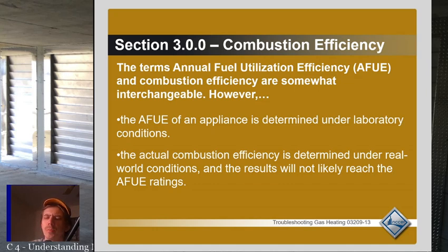Or if you need to know your BTU output in general, you need to know the AFUE of the furnace so that you can calculate what your actual output is. So if it's an 80,000 BTU furnace and your AFUE is 80%, then that 80,000 BTU furnace will actually put out 64,000 BTUs, right? But really, you're not even supposed to do that.